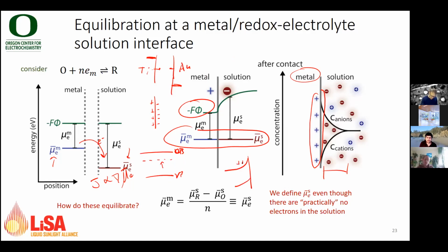Well, you get that because you don't actually have any free positive charges, or you have very few in N-type silicon, because you only have majority carriers, or electrons. So when you try to build up positive charge, you have to build up positive charge via the ionized dopant atoms, which are spatially separated. And so that's why you get a depletion width.